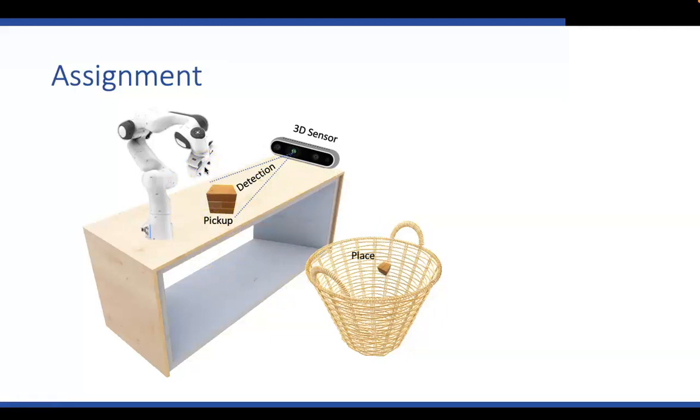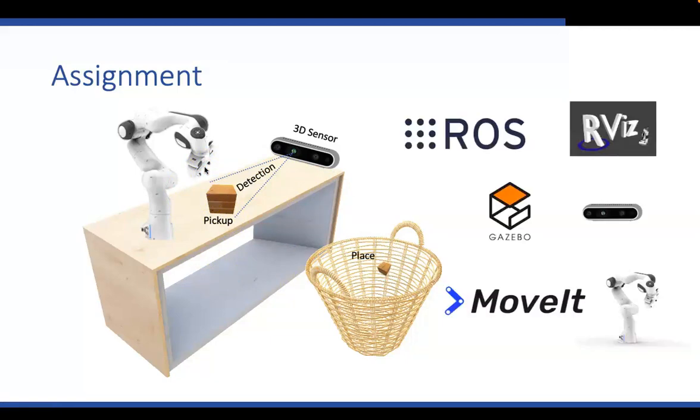To change the functionality or the joints detection, also the mechanical functionality, we will be using Gazebo. ROS is our system integration. It's like a middleware. Everything will be integrated in the ROS architecture, or ROS environment, as you can say. And then we have a 3D camera. This is an Intel RealSense camera that will be used for our detection. Don't worry, we will give you the point cloud for your own version so that you do not have to have a 3D sensor at your place.